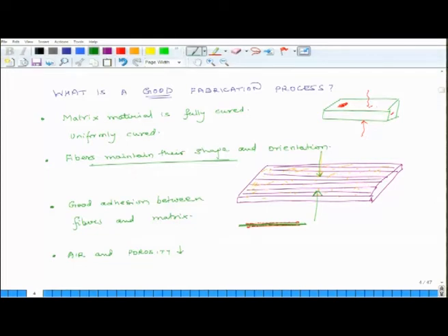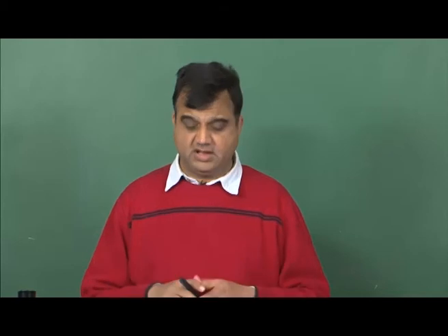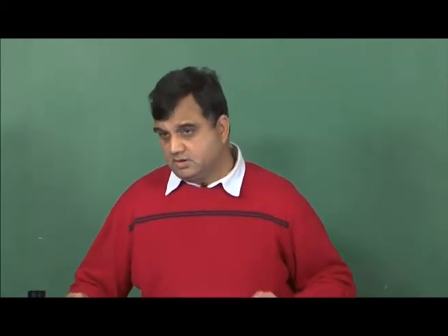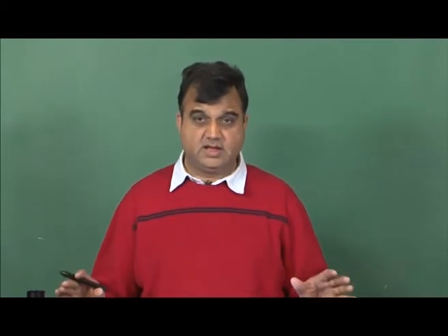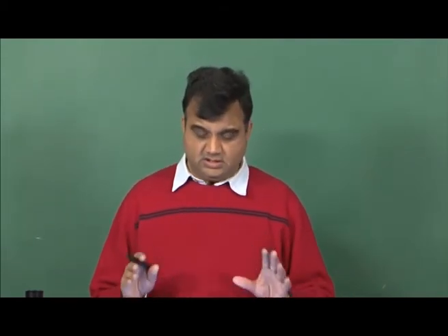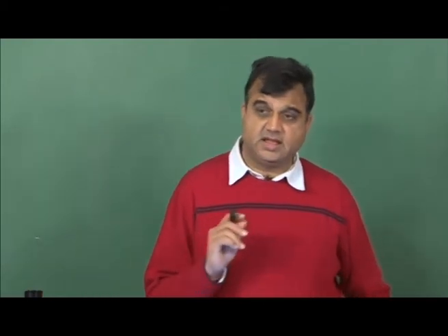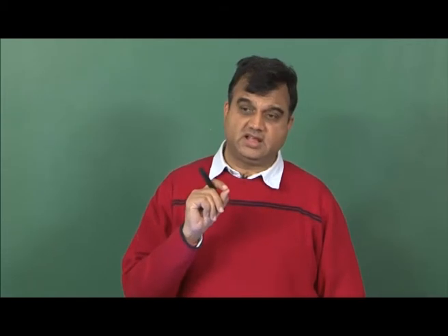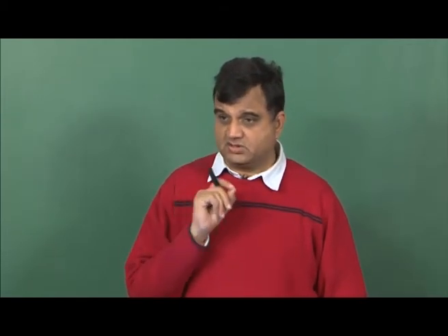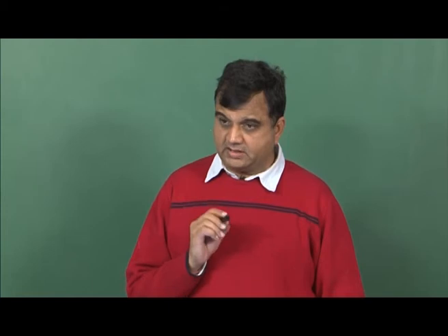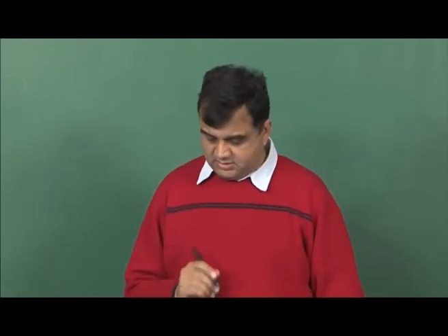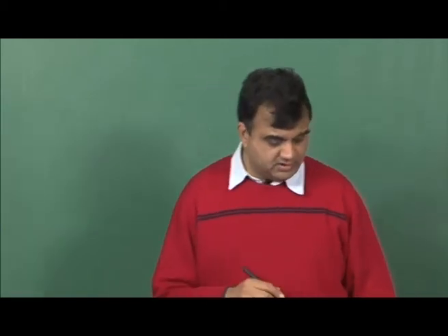By default there will be air to begin with between fibers, and we want that when the matrix flows through it, all the air should be removed, and there should not be any gaps or holes in the thing, because if there are air pockets or porosity in the system, then those could act as points of stress concentration, and at those locations you can have initial fractures in the system. So, we do not want that.